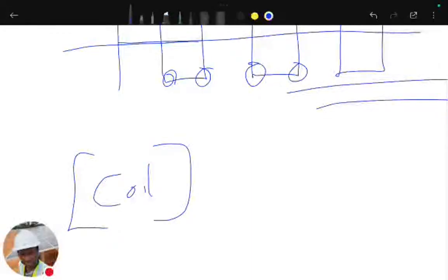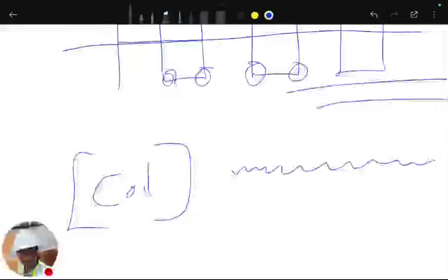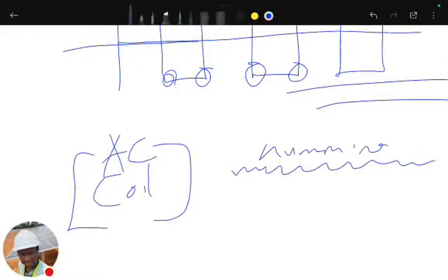So I hope someone can help me with that. Any device that has a coil in it and you run it with a modified sine wave will make this humming background sound. You know the way a clipper that the barbers use to cut your hair sounds, that's the way things such as fans sound. Well, not all fans. There are some smarter fans that they are making nowadays that are suitable for solar. I think they call them DC fans. Anything that has an AC coil, let me emphasize that, anything that has an AC coil in it will make this humming background sound. And this humming background sound can do two things, or three things.